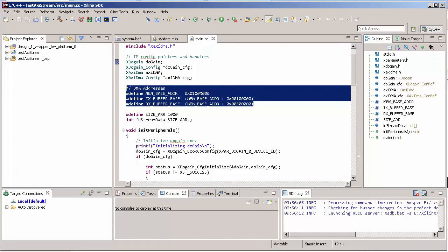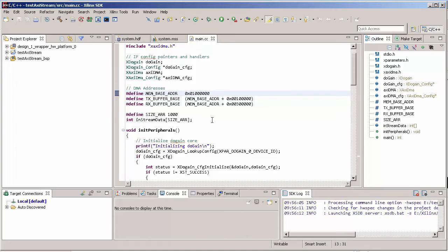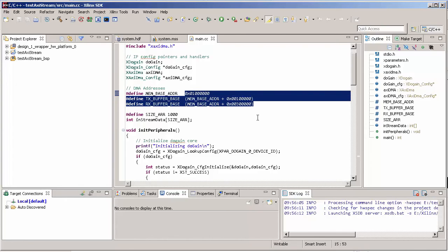So basically here we are just defining our place in our DDR that needs to be kind of far away from your code. That's going to be like the scratchpad of our DMA. Our DMA is going to work on this address, and it's important that you don't put an address that is near our code, because if you do this, the DMA will basically screw up your program.